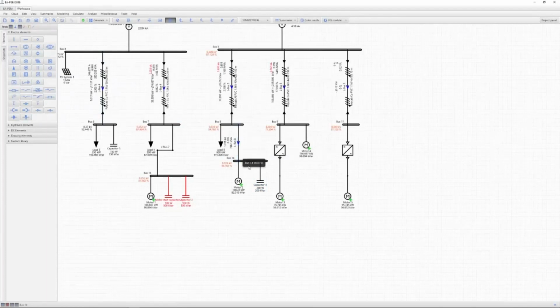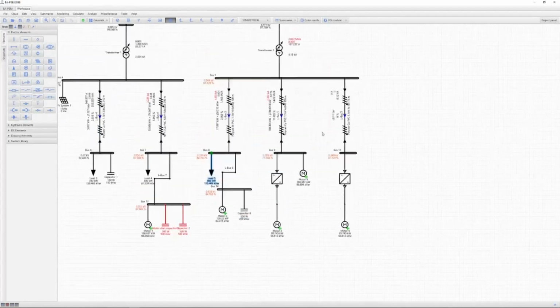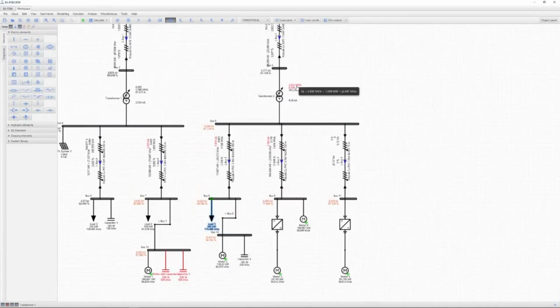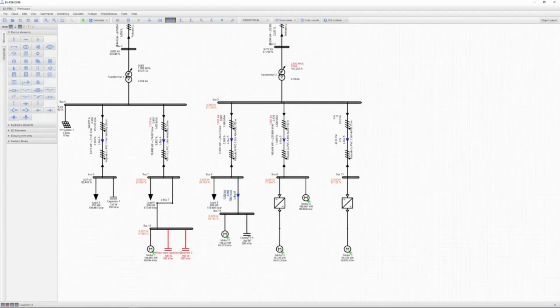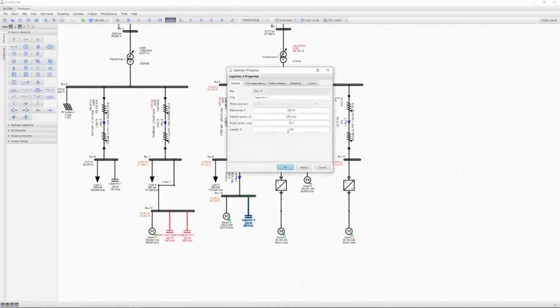As we can see, still a lot of reactive power is generated that should be compensated because reactive power costs, and we can see our transformer is overloaded, and in time insulation could be defected because of non-nominal temperatures. So now let's add more capacitors, or let's just increase this one's reactive power, because this is just a basic simulation.